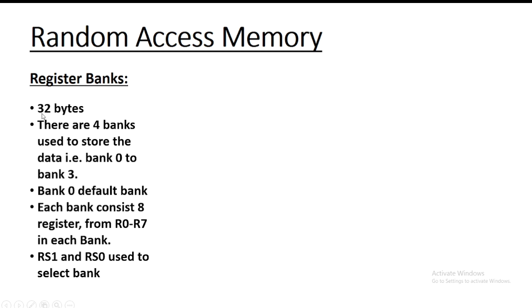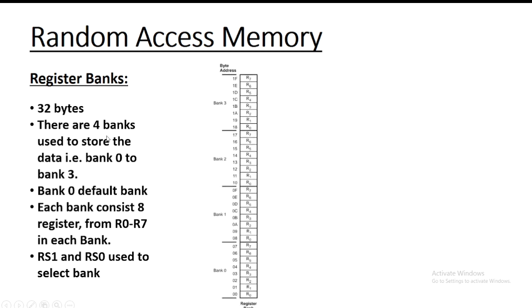The size of the first section is 32 bytes, and in that 32 bytes there are 4 banks: bank 0, bank 1, bank 2, bank 3. Bank 0 is the default bank. When the microcontroller is reset, bank 0 is selected by default.